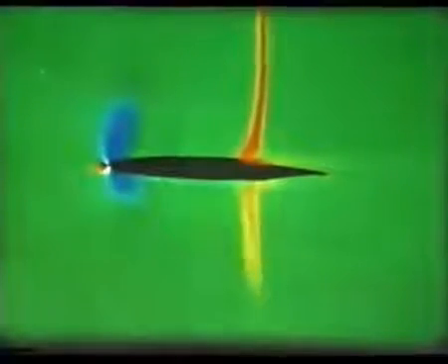The energy wasted as heat in the shock wave must be continuously supplied by the engines. Otherwise, the aircraft would decelerate. So as the aircraft approaches the speed of sound, it meets an additional kind of drag called wave drag. Wave drag is a large proportion of total drag at transonic speeds. As the speed of airflow is increased still further, the region of supersonic flow goes on growing larger, and a second supersonic region starts to form on the lower surface of the wing with another shock wave.